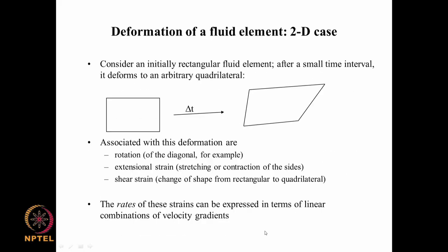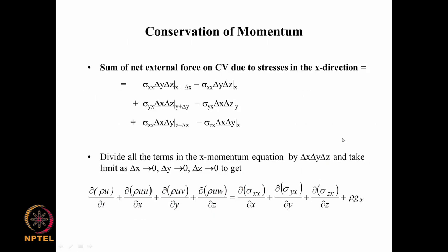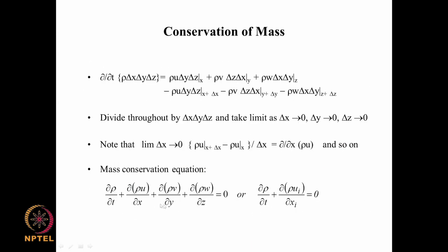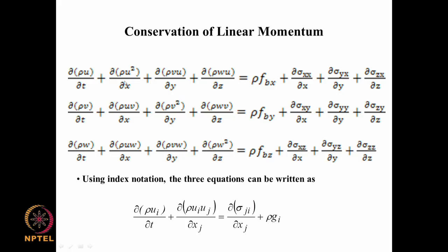So, you have 4 equations, and how many variables are there? Here you have 3 variables because u is u, v, w. If you look at this set of equations and the continuity equation here, in the continuity equation you have rho u, v, w. Okay, you can say rho is the density of the fluid and I should know it. So, you could say that or it is given independently, and so you have 3 variables u, v, w here, and in these 3 equations you have u, v, w.